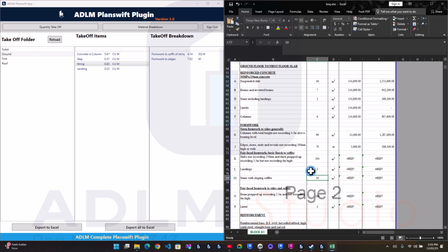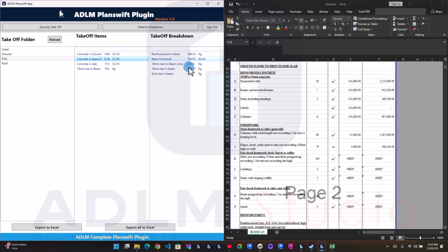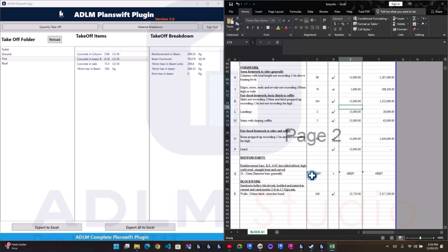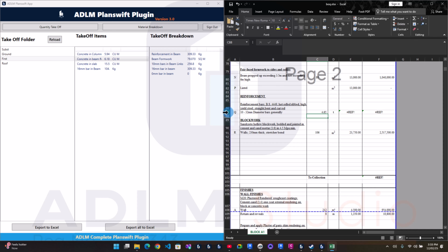That's 5. Beam formwork. First floor beam formwork. That's 79. That's 80. Lintel we don't have that yet, so take that off. Equal to this. Good. So we are done with that. Our reinforcement. Also, I'm using a factor of this here. So you can use this factor for fast, or if you don't use factor, you can just take it the long route.